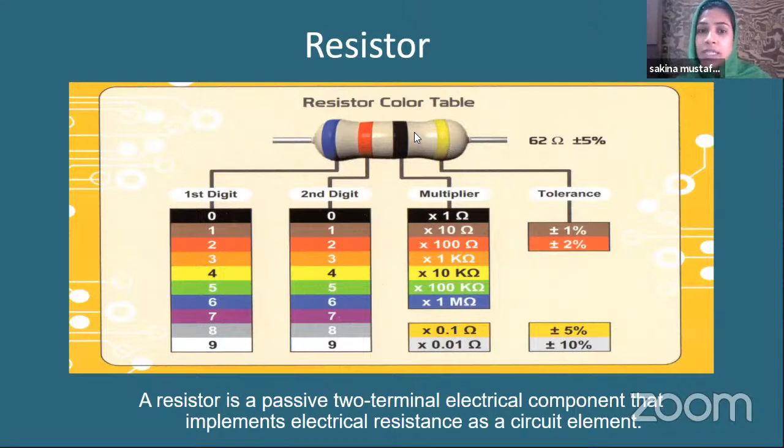Now, for example, 220, right? We require 220 ohms. So this was the red, right? 2 is red. This was the color red, and you can see that was a brown. So 220 ohms. Again, I will go back and tell you that we have used the 220. So 220 means this was the red color, this was the red, and this was the brown. So we come to know this is a 2. So yes, we have to learn this chart if we want to know the color of the resistance and how many ohms it is. It can be easily learned.